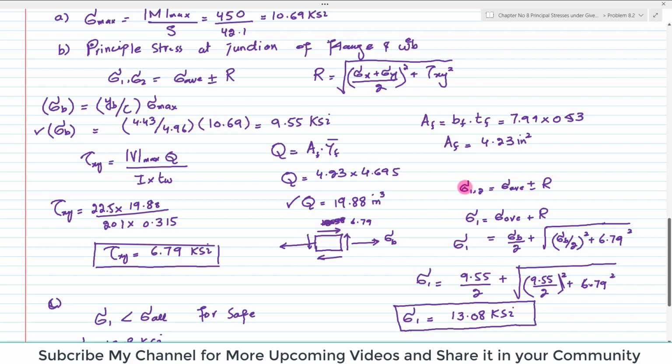So for principal stresses, we know that sigma 1, sigma 2 is equal to sigma average plus or minus R. We need the maximum value, so we will take the plus one. So sigma 1 will be equal to sigma average plus R. And we know that sigma average is equal to sigma x plus sigma y divided by 2. So you can see here you have only a single stress, that is sigma B, and sigma y is equal to 0.